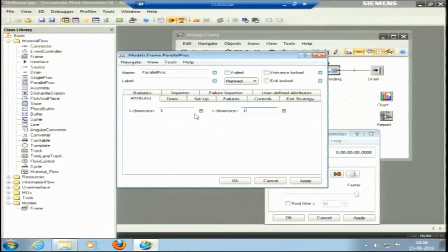Now, when there is waiting, when there is blocking, we can think of adding new machines, or taking a few machines off, and if there is a lot of waiting time, sometimes we can even think of doing some other processes, like I have said in case of the process layout. In a process layout, we have a specific set of machines in one section, another set of machines in another section. If we see the overall machine time, and in this specific section, for 30% of the time there is a blockage, or waiting, we can consider that 30% of time as waiting, and we can give them some other job.